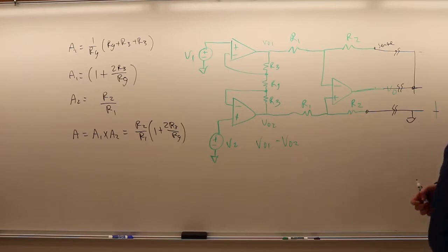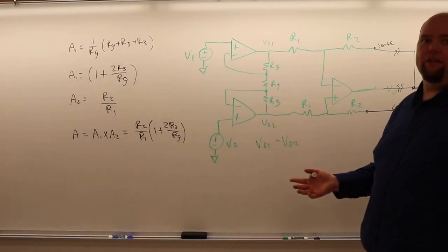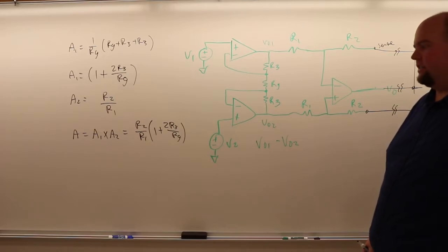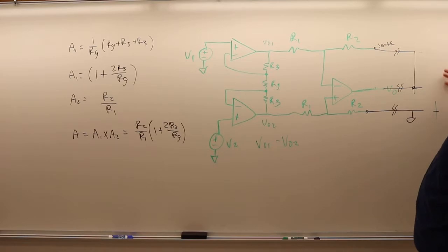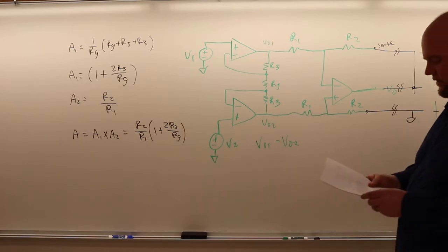Analog signals in general, we don't like to have them go very far because the longer they go, the more they pick up noise, the more they pick up undesirable resistances and capacitances and inductances. But this is one way that can help us clean that up. We can just use the internals of this design to help make sure we have a nice, clean, coherent signal at the other end.